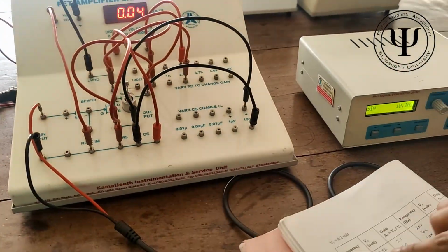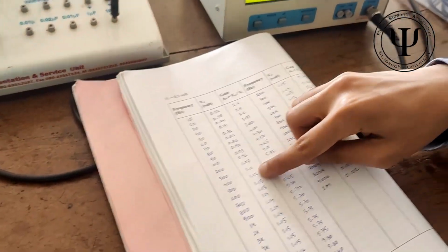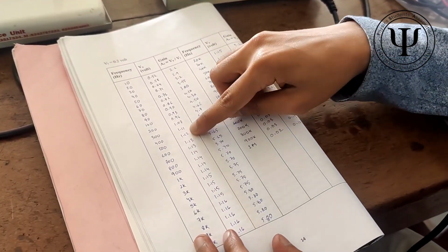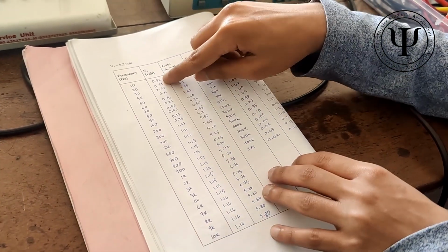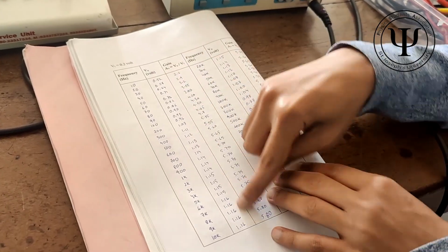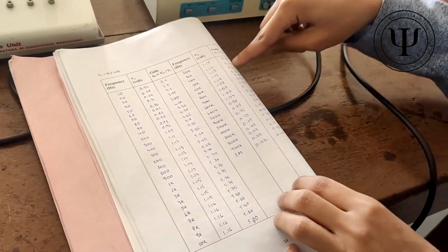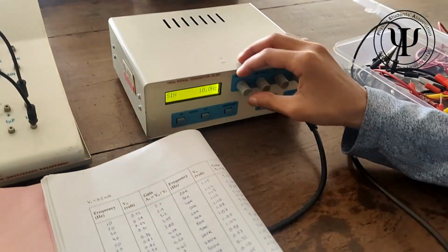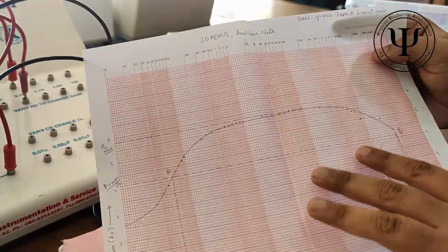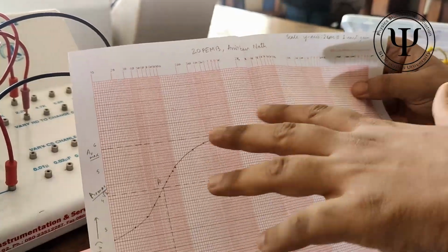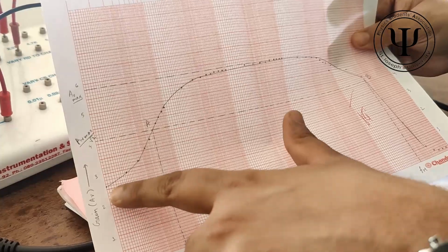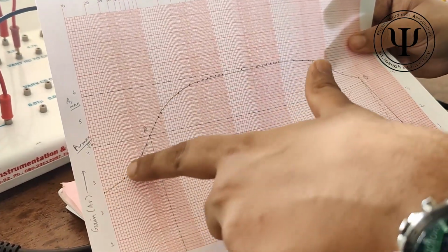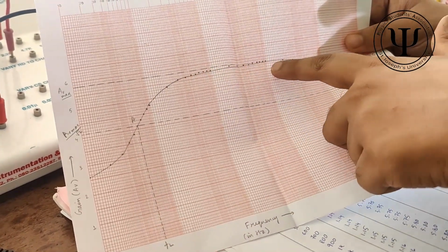What you need to make sure is that as you increase the frequency, you're going to notice a plateau. That is a very little change in your output voltage as you change your frequency rapidly. So it's going to start very low, and it's going to increase, and then it's going to stay stable for a while, and then it's going to come down again. This is how the graph, basically the plot between the gain and the frequency, will be. So basically the values will first increase to a certain point, then it will be a constant value, and then it will decrease.